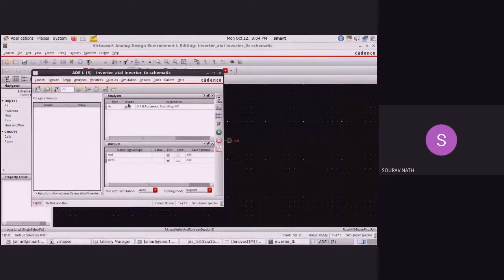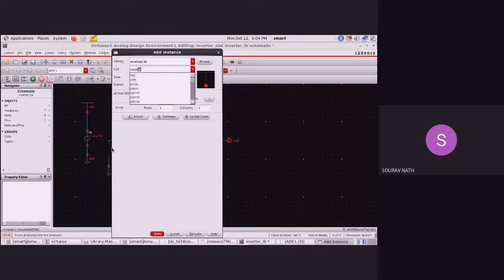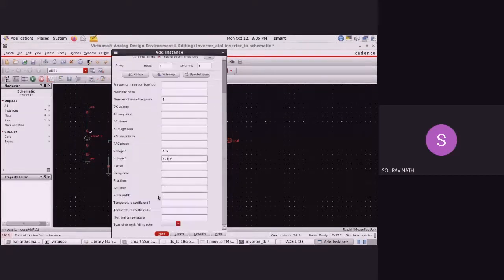Now let's do transient analysis. So disable this DC analysis. Then you have to give a transient source. To cancel the previous command, press escape. So give a VPULSE. Let us configure this pulse. Maximum voltage is 1.8. Period say 200 nano. Rise time typical 10 pico. Fall time say 10 pico. Pulse width half of the period to maintain a 50% duty cycle of the pulse.